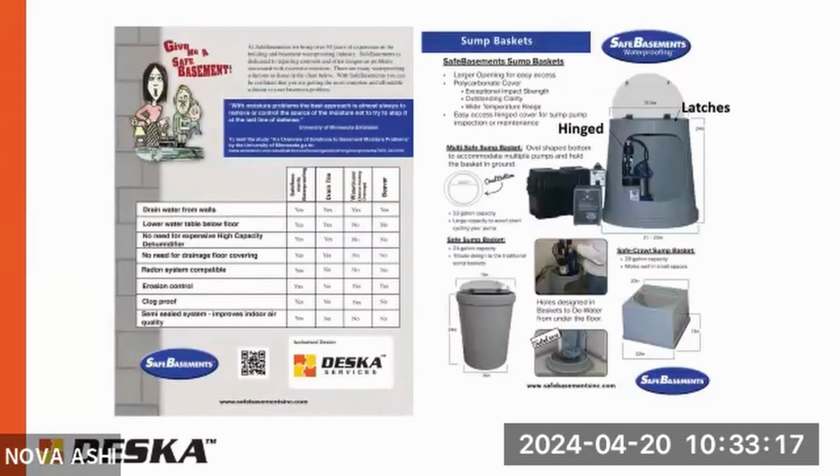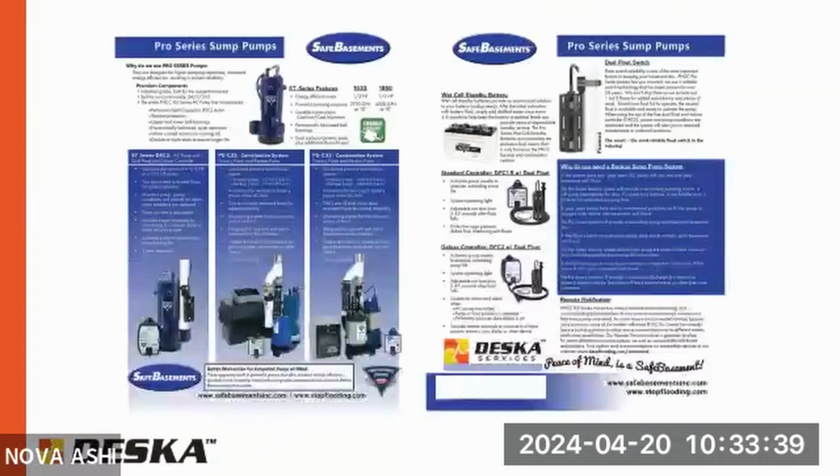I'm sure you guys have probably seen a sump pump with a basin that is all bolted down. Do you typically unbolt it, or you don't touch it? Okay, yeah. So we typically would recommend one that has a hinge lid that's also radon sealed, so that way you can actually inspect and service the pump, rather than if there's an issue, it might take an hour to figure out how to get to the pump and test it.